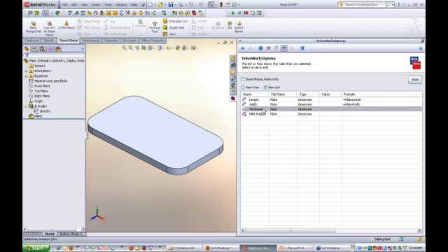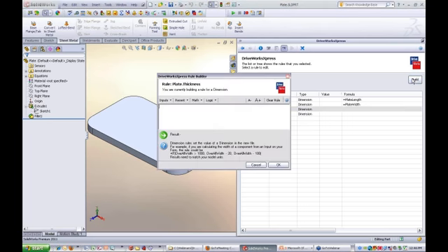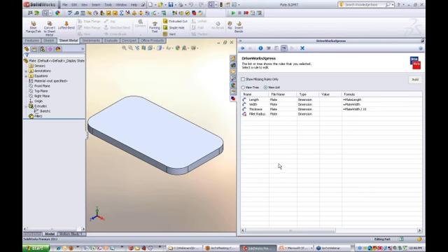The thickness we know was supposed to be 1/10 of the width. So if we build that one, that will simply be the plate width, and I can type it in or choose from a list here, divided by 10. So a very simple equation, just to show you the concept of it. It's okay for that. So we have 3 of our 4 dimensions controlled with formulas.